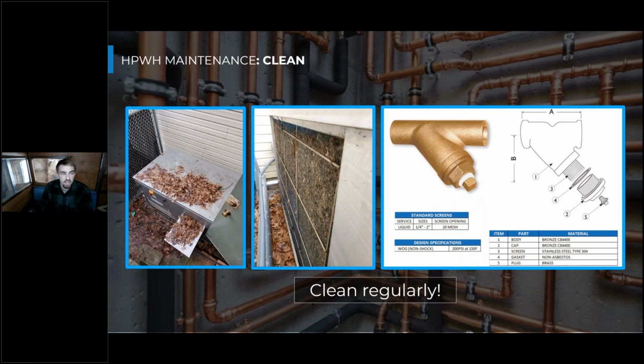And in terms of cleaning these heat pump water heaters, you might see actual physical debris in outside installations, like you see here with all of the leaves that have accumulated in the fall and have been taken up into the air filter. Because this air filter is so clogged, now the heat pump can't intake all that air that it's harvesting the heat from, so it's not going to be able to operate as efficiently.